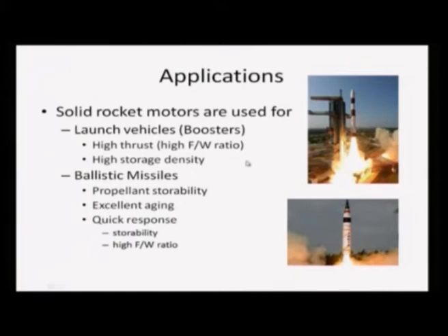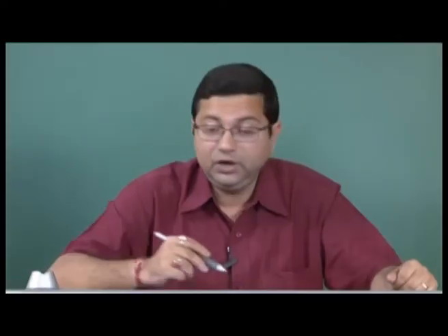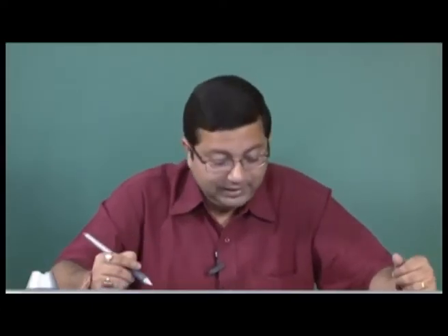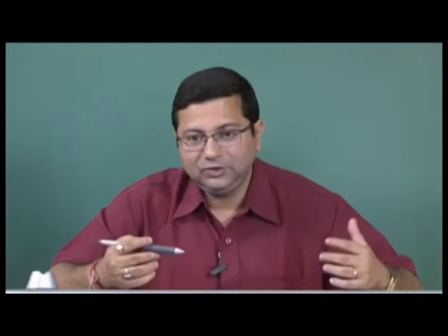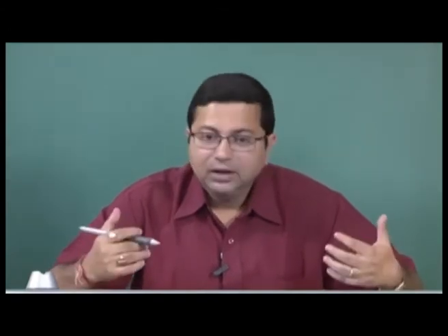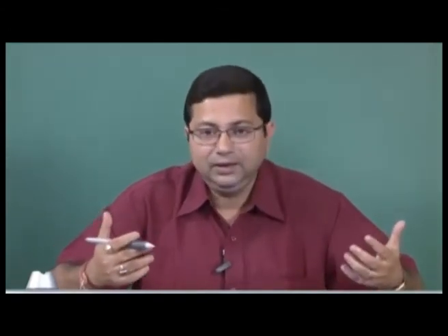However, they are very extensively used for missile applications, particularly ballistic missiles, because of the propellant storability which I have just discussed a few minutes back, then the excellent aging process and quick response. So, they can be kept ready and they can be lighted very easily. Unlike a liquid propellant rocket, where you require a lot of preparation time just before the launch, as we will discuss, solid propellant rockets do not require any preparation time.